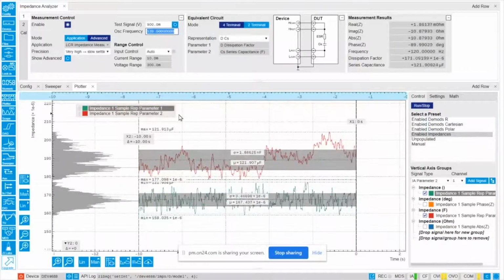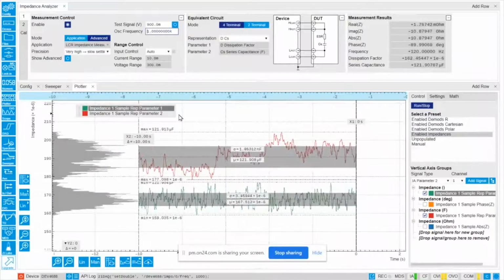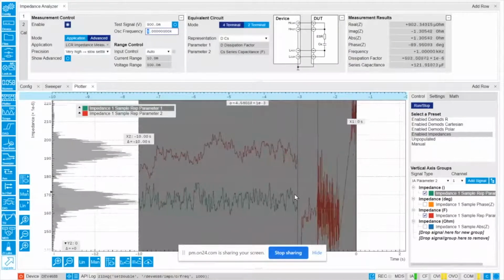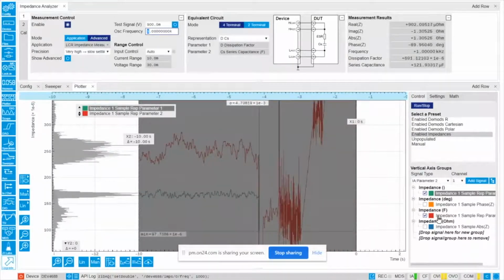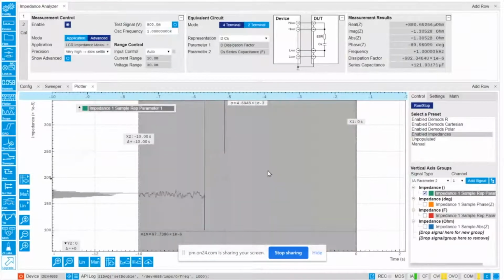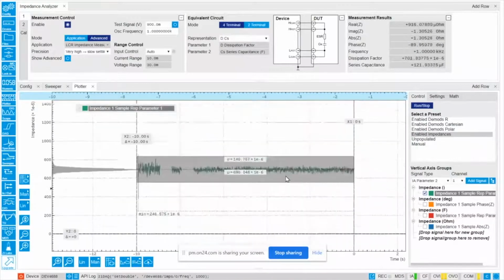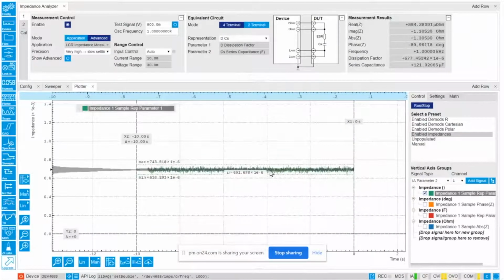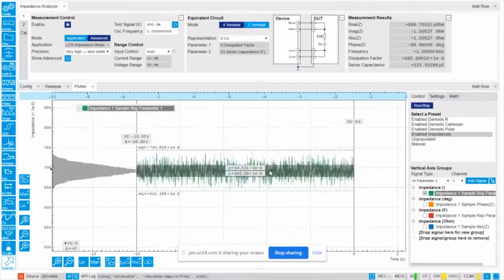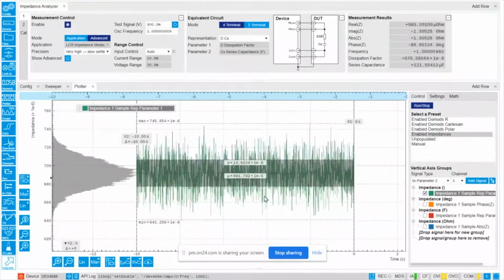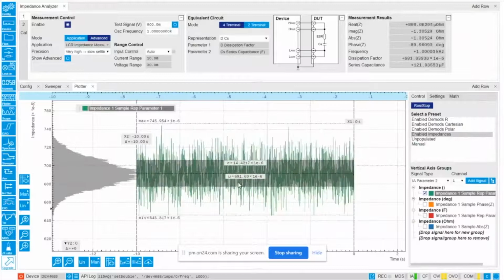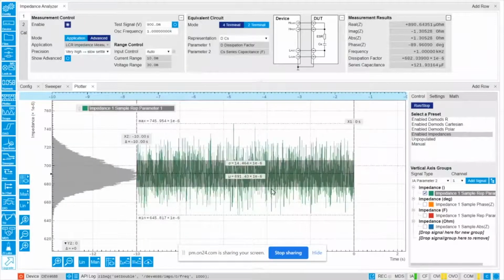Let's crank that up to 1 kilohertz. There's a little bit of a step response there in the plotter, so we can get rid of the first trace. That has changed it significantly. There we go. After it settles, you can now see that we're measuring the D at 1 kilohertz, and it's increased significantly. It's now 6 times 10 to the minus 4.